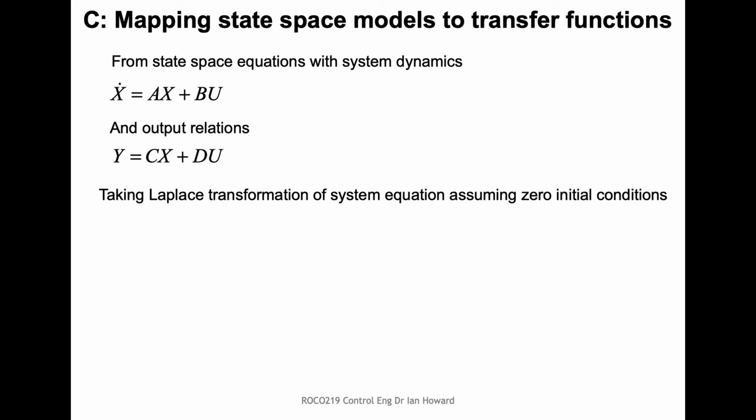Transfer function is then going to be the output divided by the input, remember? So it's going to be y divided by u in the S domain. So first of all, we need to get into the S domain. And since we're interested in transfer functions, we don't have to worry about initial conditions when we take the Laplace transforms. So just as we would for scalar or single variables or one-by-one matrices,